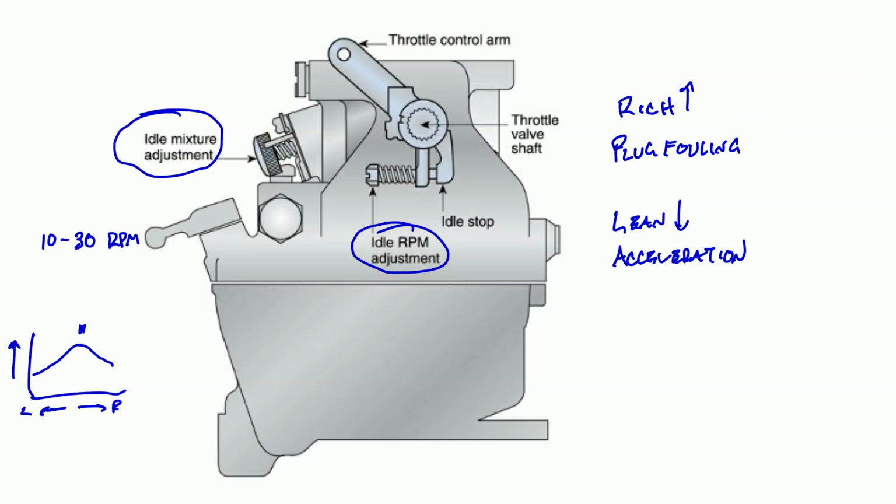So again, if you're quick on the mixture lever, you can pull that all the way back, watch that rise start, and before the engine dies, you can push the mixture back in to full rich and catch the engine before it dies. That way you can make adjustments back and forth as you're working on the aircraft. On the other hand, if it's not particularly accessible or it's dangerous to try to get at while the engine is running, then we can just shut the engine off completely, make a couple adjustments to the screw, come back and try it again.